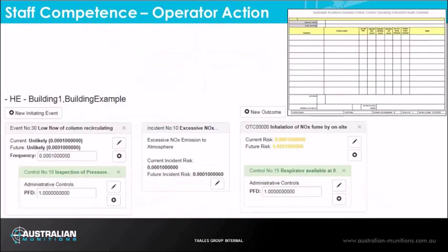When we looked at a performance metric for staff competency, we created the Operator Critical Action Assessment. The Operator Critical Action Assessment is the most labour intensive of our checks. To create this check, we went back to our LOPA study. The process requires that our MHF risk assessments have adequately detailed the operator critical action in a process.